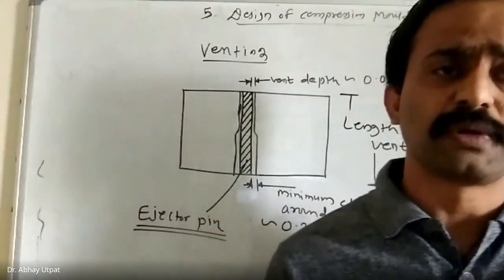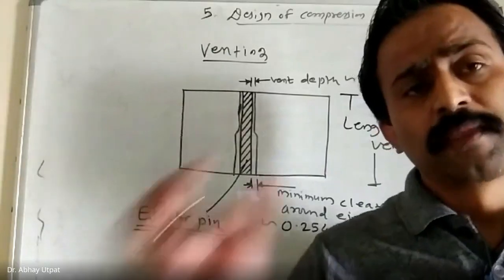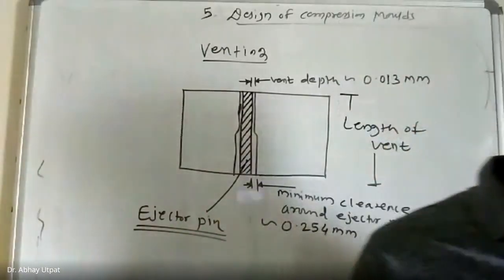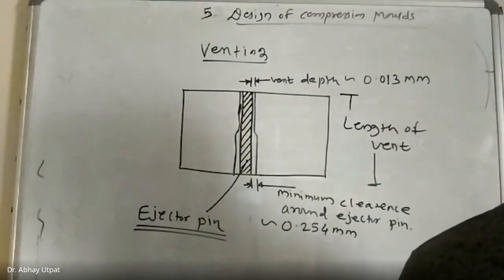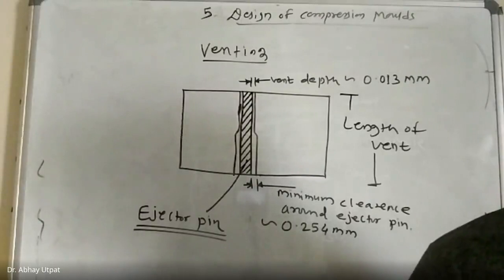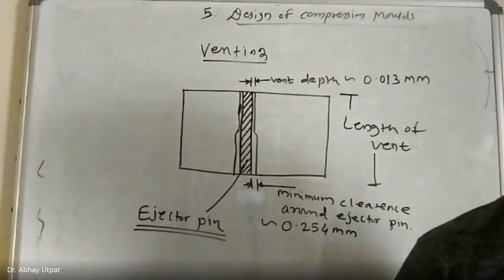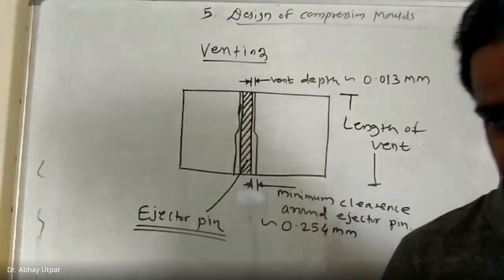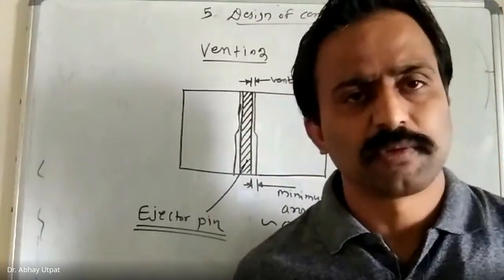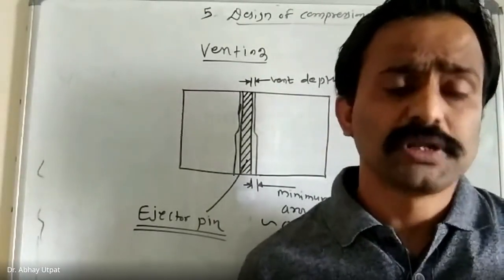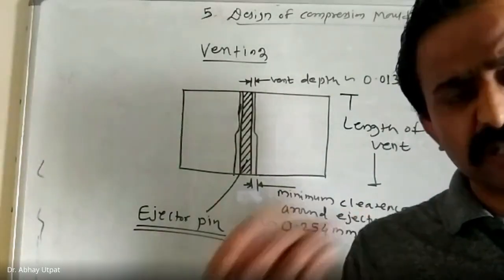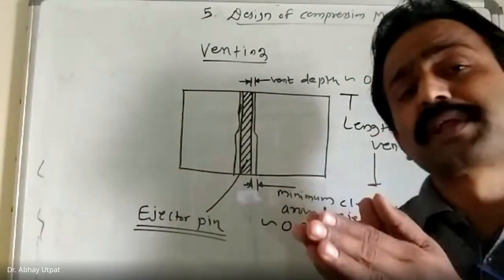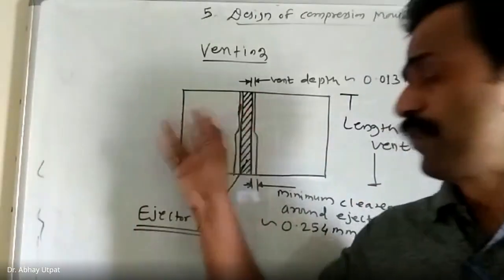The second thing which I have explained is that if the source of heating is an electric cartridge heater, the heating tolerance is not achieved, and that's why steam is considered the most efficient heating medium for molds. Compression molding is usually used for thermoset plastics. Once you heat that plastic component, whatever steam and gases are produced must be relieved outside, and for that purpose, vents are provided.